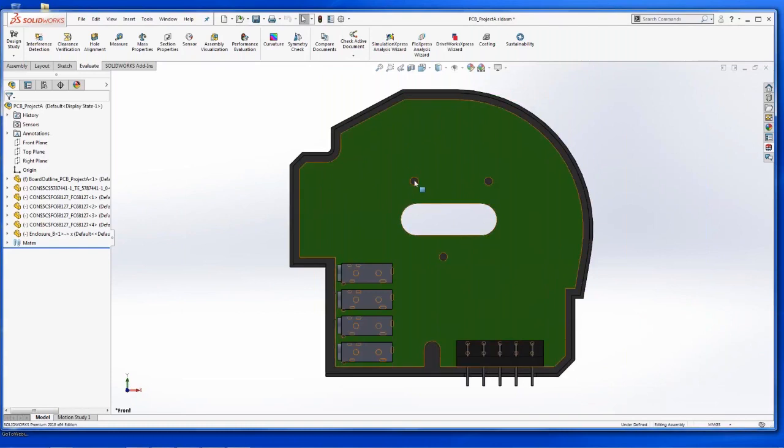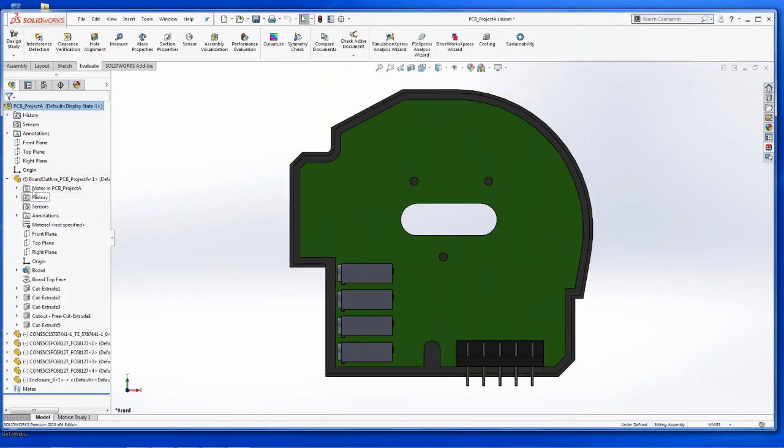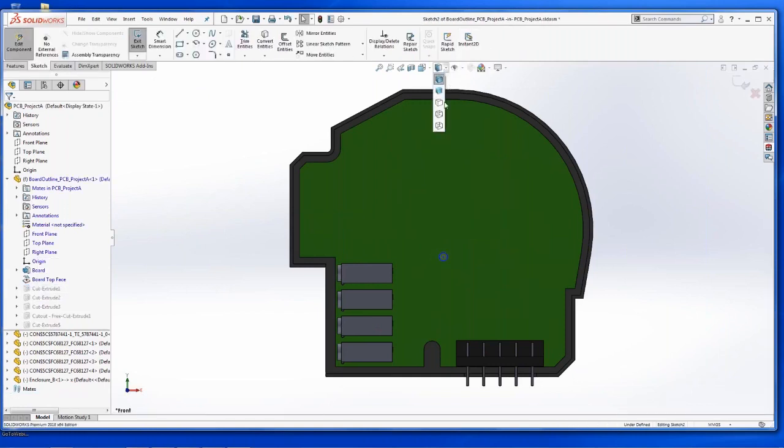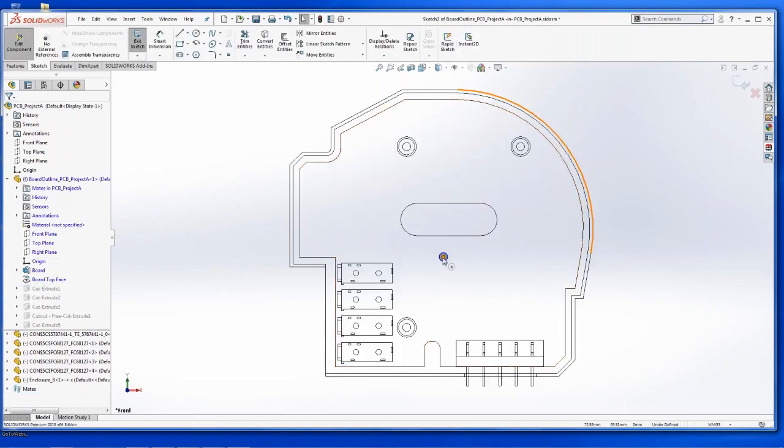But before I do that, I need to move these mounting holes to match my standoffs. So inside of the board part, right, the separation between all through holes and models occurs. So all the holes are now part of the board part, but the models remain individual SolidWorks parts. So we just simply edit this sketch. Okay. We can change our view to the wire mode.